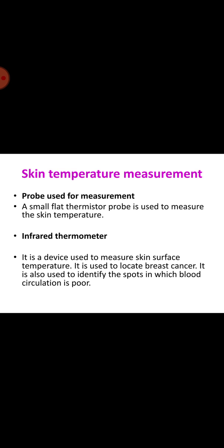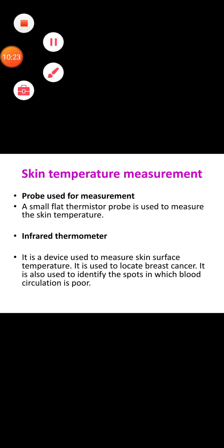This measurement is based on the development of a new type of sensor called the pyroelectric sensor. A pyroelectric sensor develops an electric charge that is a function of its temperature gradient. The sensor contains a crystalline flake which is pre-processed to orient its polarized crystals. Temperature variations from infrared light striking the crystal change the crystalline orientation, resulting in the development of an electric charge. The charge creates a current which can be accurately measured and related to the temperature of the membrane.